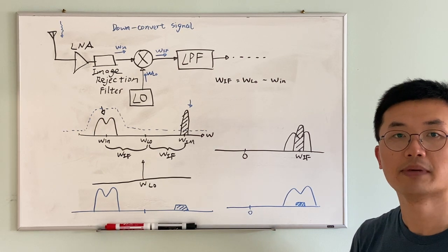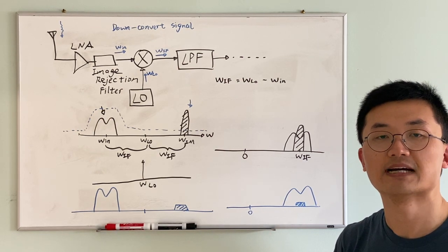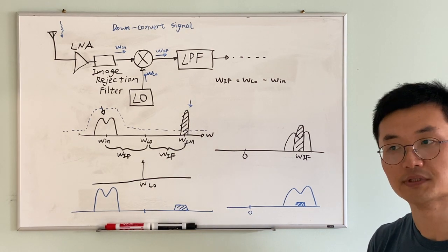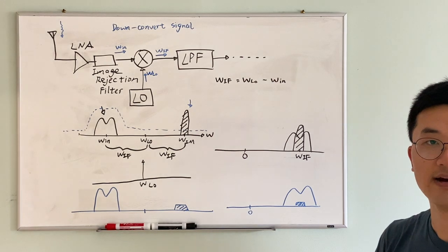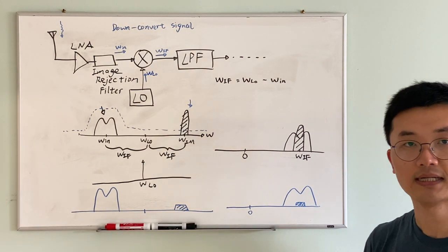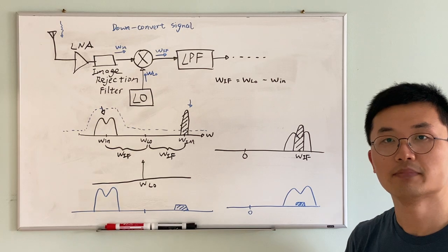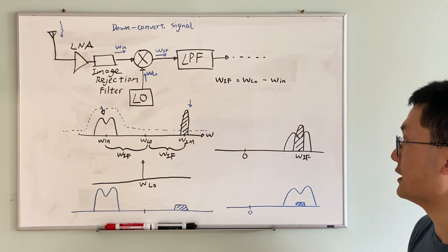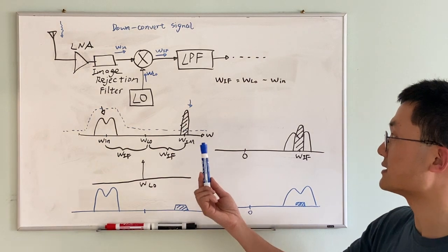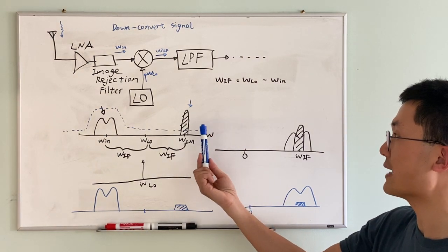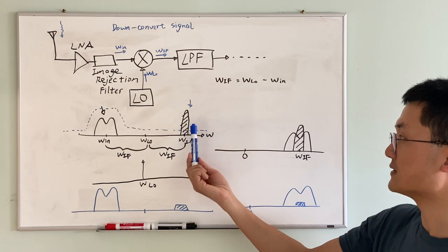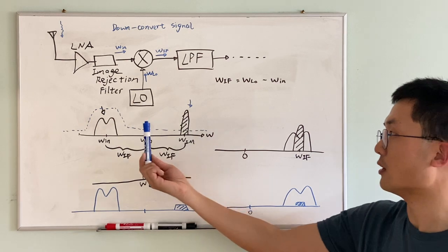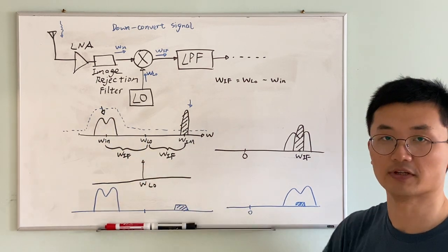There are many communication devices, technologies, and standards operating around this frequency range, including Wi-Fi, Bluetooth, satellite radio, and various different types of cellular mobile radio. So you shouldn't be surprised that some of these technologies happen to have spurs that fall exactly in the image frequency of your signal of interest.